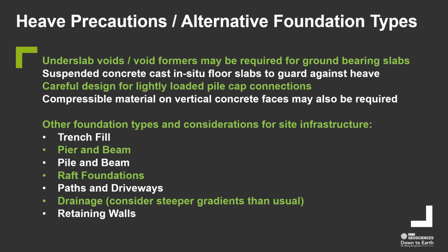I think that, you know, trench fill, pier and beam, so really just a deep trench filled vertically to form a pier and then put a beam on top of that, or put an actual pile in the ground instead of a pier and then put the ground beam on. Raft foundations need a significant granular cushion to ensure you've got enough protection against any expansion trying to lift the concrete floor level up.